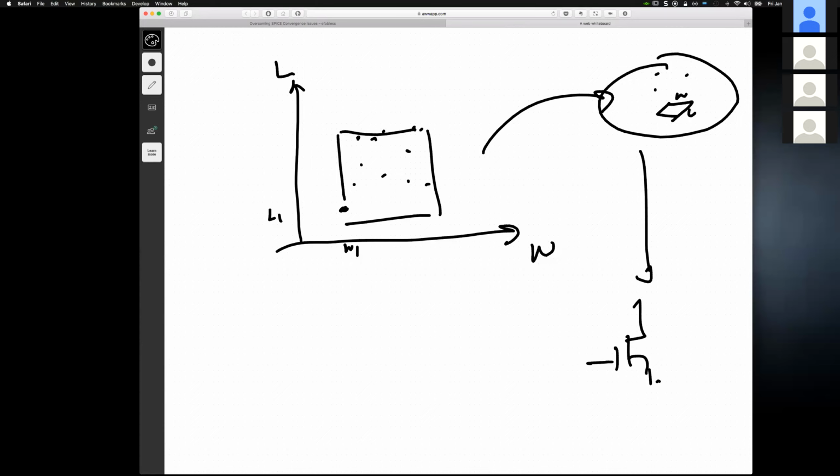And you can see that in most of the foundry technologies, they have the effect of binning. So they would say, this one is bin 1, and if you exceed a certain W or L, you go to a different area, and they characterize it differently. Now, the problem that happens is that when you're fitting the models, depending on which process and which effect, there probably won't be one that fits all.